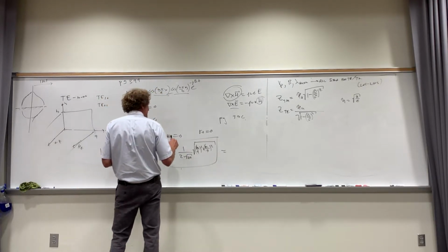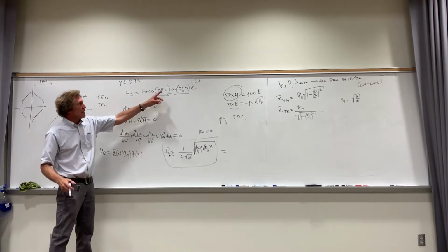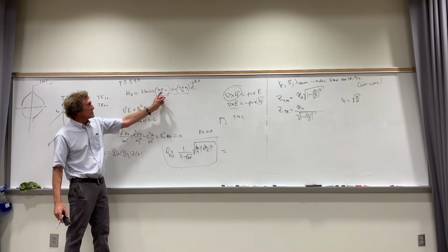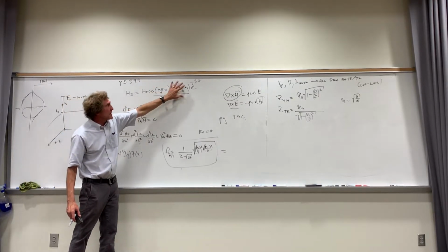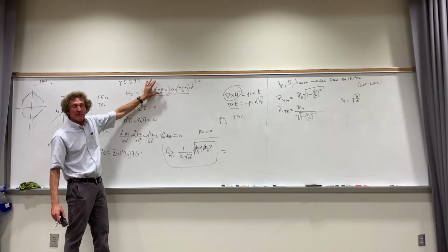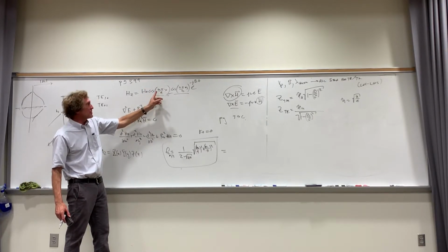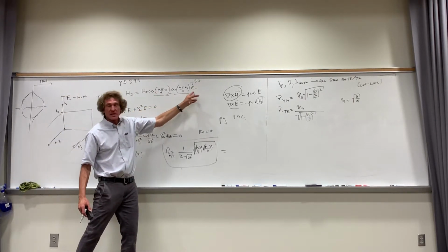When we have the TE mode here, I can't have M and N being 0, and here's why. If you look at this, if M is 0, this cosine just is 1 all the time, right? If N is 0, that cosine is 1. So the E or the H field doesn't vary with X or Y, neither with the E field. I just have this, right?